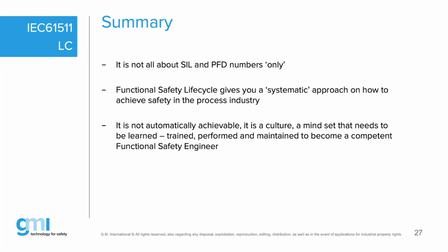And mainly the end users are struggling to prove how they will maintain this. It can look wonderful on paper, but if the end user cannot maintain the plant to these performance numbers, it doesn't make sense to even produce a report. The functional safety life cycle is not just to make your life miserable and tell the engineer to do it this way. It's purely an attempt to give you guidance on how to prove it on paper, how to check it, how to verify, document and assess it, etc.